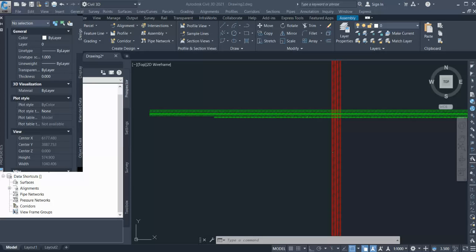First thing, an interchange only needs to be provided when you have two major roads. Suppose you have two national highways crossing each other, or two state highways or expressways. In that case, you have to provide an interchange because an interchange is a costly option, so it's only provided on two major roads.